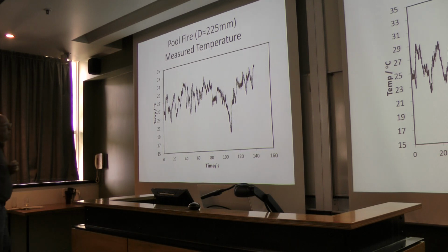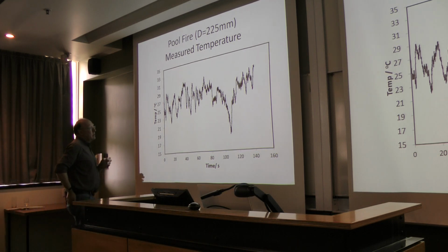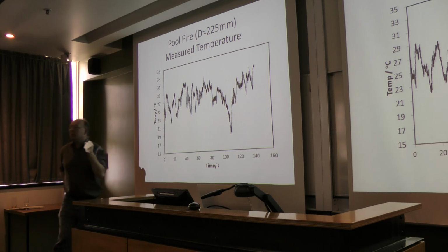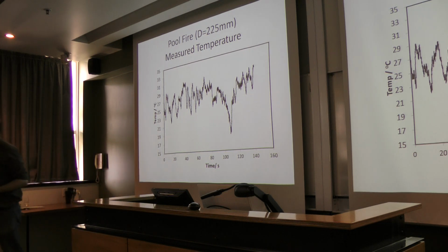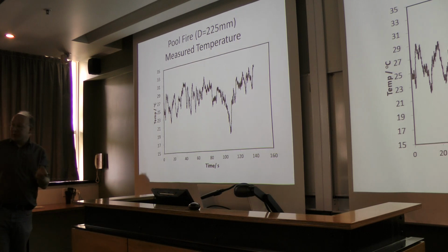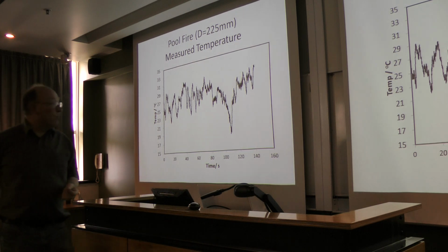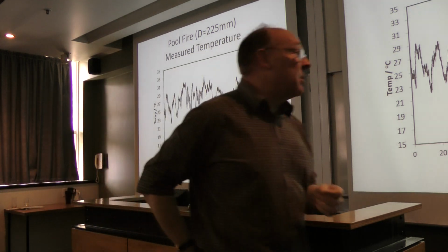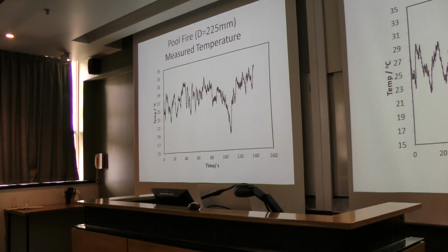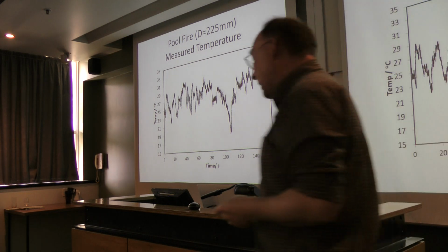It's not quite heptane, but think of it as heptane. And we're logging at 100 Hertz, which is absolutely fab because we're looking for something about 3 to 4 Hertz. So we're logging quickly enough. The question is whether the thermocouple is sensitive enough. Now, at the moment, I haven't attempted to apply the lump capacitance model to this. I suspect it would fail miserably. Okay.